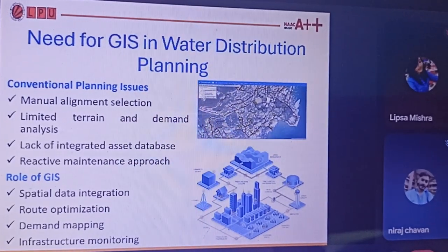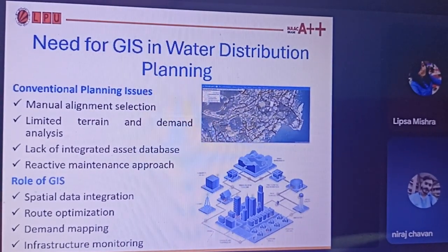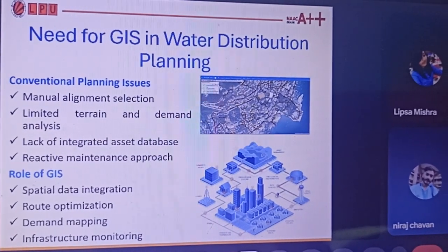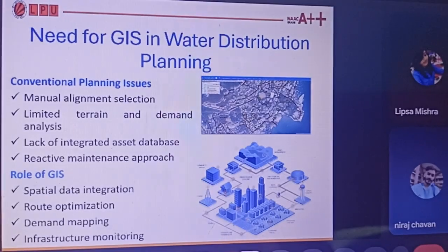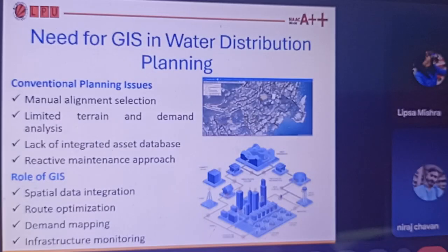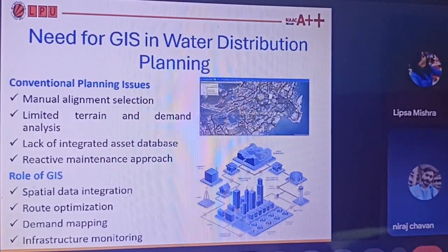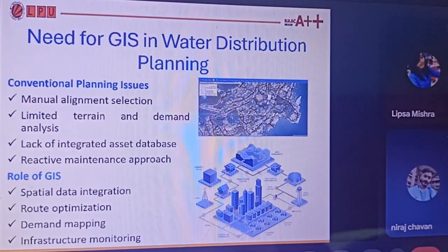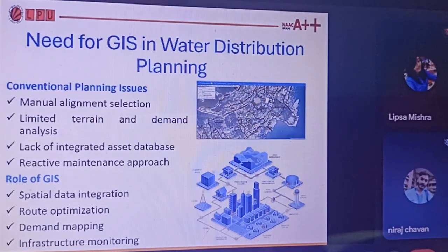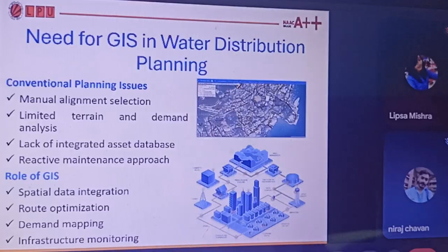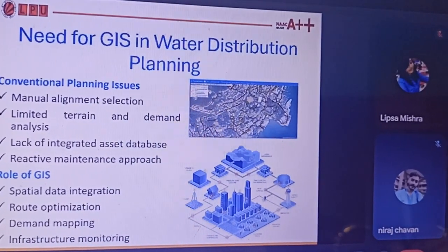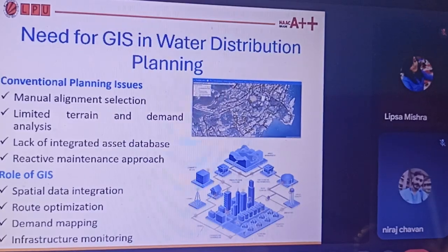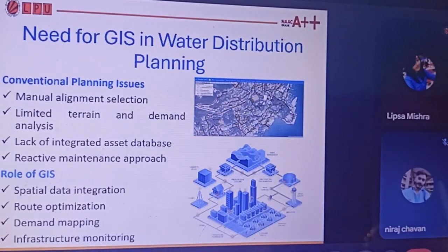First we lay the sewer pipelines, where the dirty water from your home comes out, and above it we lay our water pipelines which go into your house. Your sewer pipelines have a larger diameter. If you take 20 inches diameter for your sewer pipeline, your water pipelines will be approximately 6 inches, much smaller, because we are maintaining pressure inside the water pipelines.